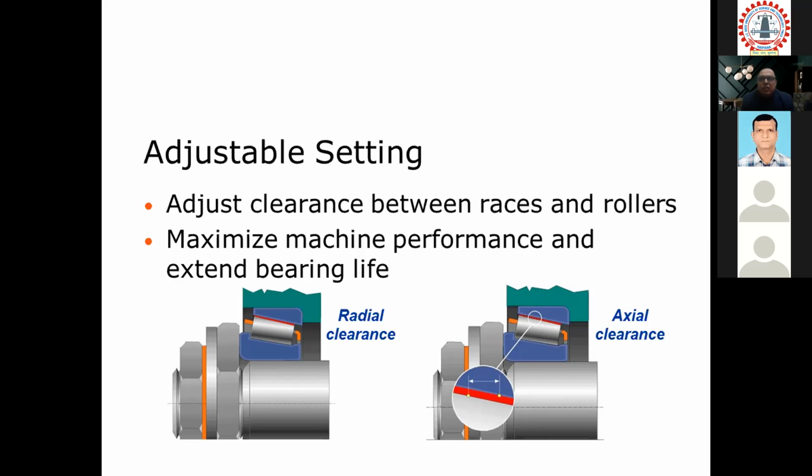and a very high amount of finish. So the raceway and the rollers, not the OD. If you look at this cup, the outer race inner part and inner race outer part, and the rollers, they are finished through the honing process. So with a combination of very high surface finish, hardness and lubrication, you are able to achieve a high life. Your third question, have I answered the first two questions? Yes, sir.